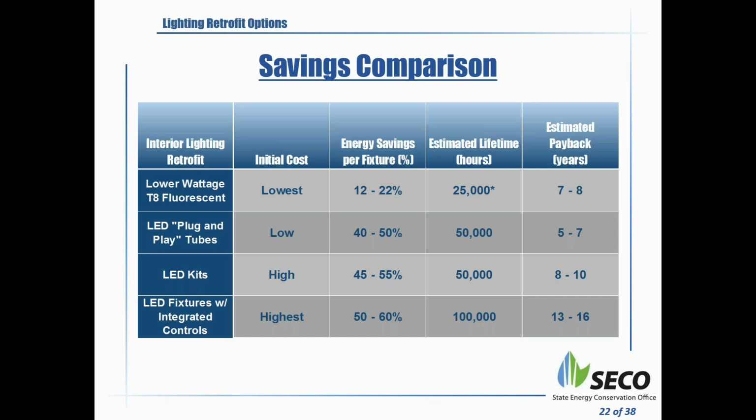The LED kits, which some people were doing, were pretty popular 2 years ago, and some people are still doing it. It's their preference. They want to get rid of the ballast. It costs a little bit more. You'll get almost similar savings to just a plug-and-play tube replacement, same kind of hours out of it, and since it costs a little bit more, the payback range is a little higher.